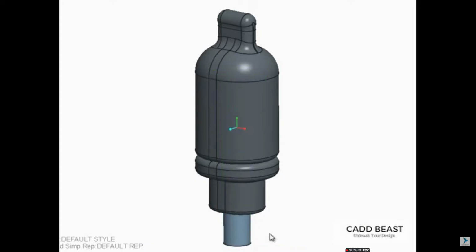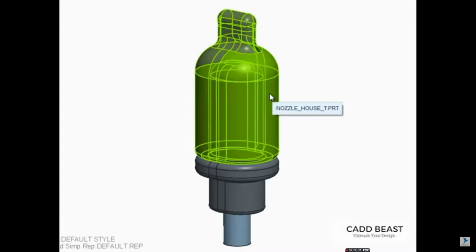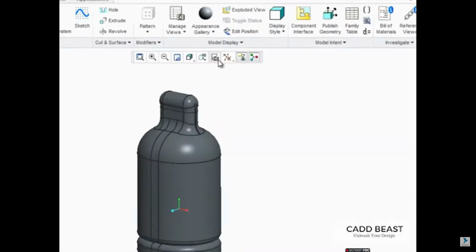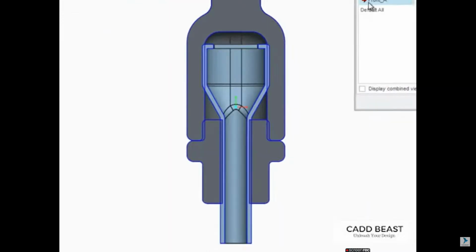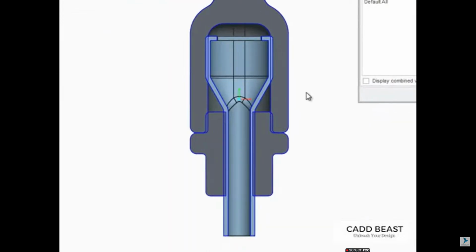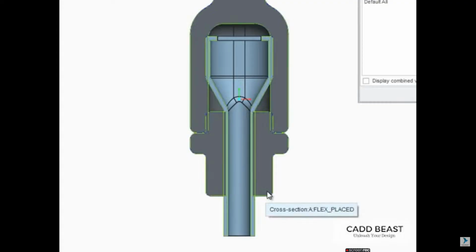Traveling through a flexible foam housing, and then the flexible upper foam housing fits over both, fitting snugly to the lower housing. However, we can see from this cross-section view that there is interference when the components are assembled. There's interference between the nozzle and the lower housing, and the lower and upper housing.